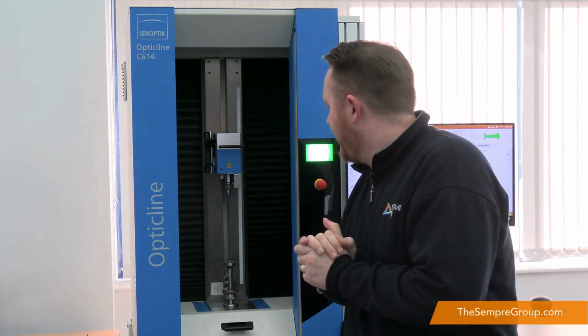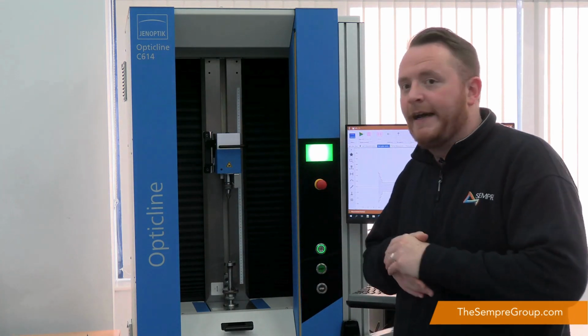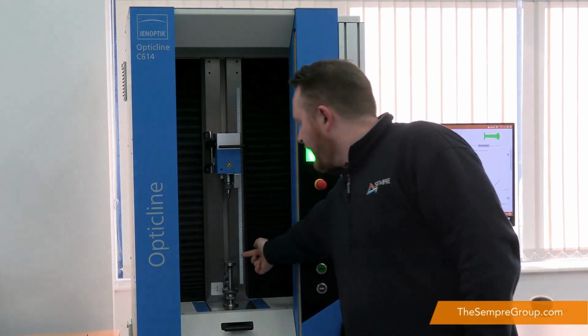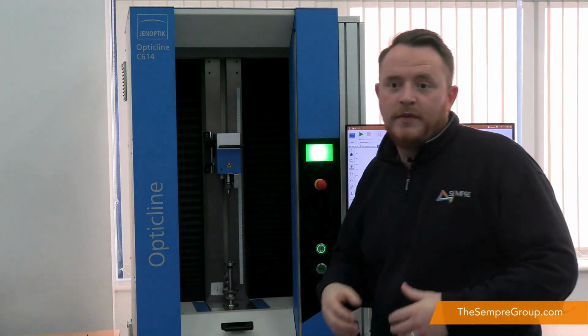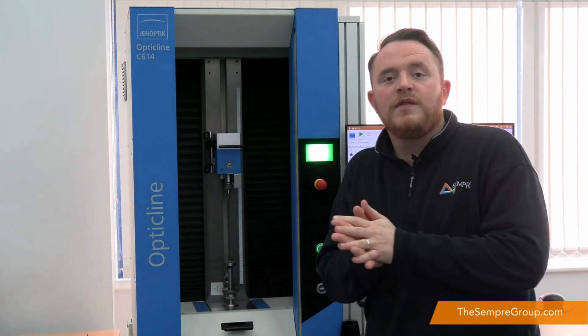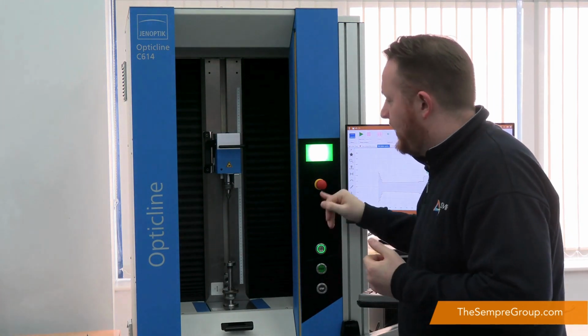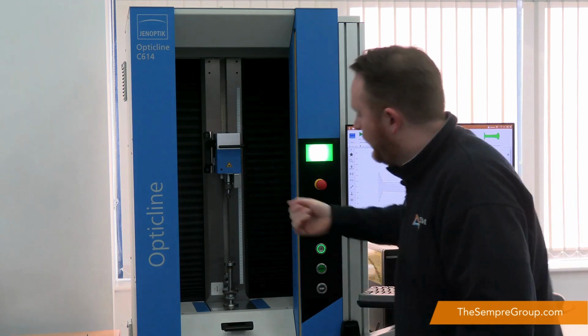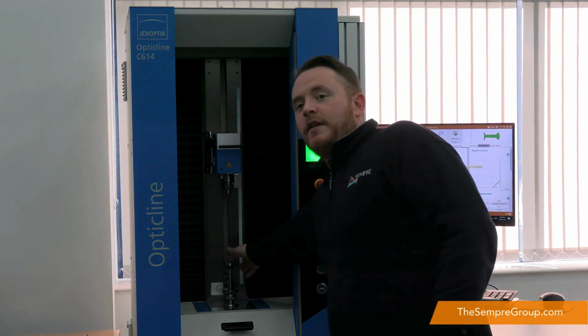So now we're going to be taking a look at some profile measurement, as well as an overview on the differences between what we can do on a cam measurement as well. So within the machine we've got a component. I've got an external profile being measured. So the idea behind that is to show you if you had a blind feature or a blind profile that we couldn't see with the optics, that we could use the probe to measure that profile, as well as also taking a profile on the inside of the component.